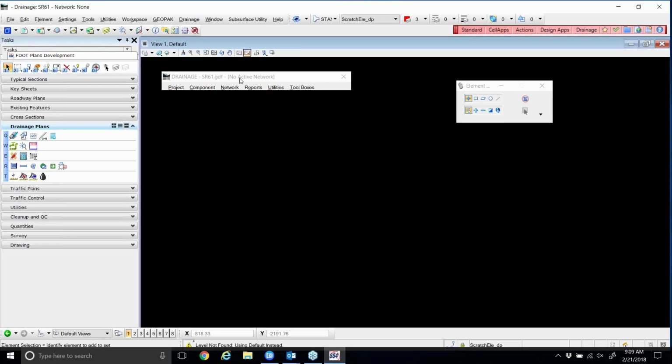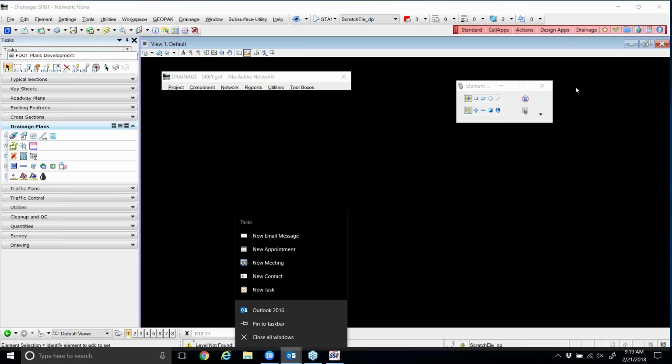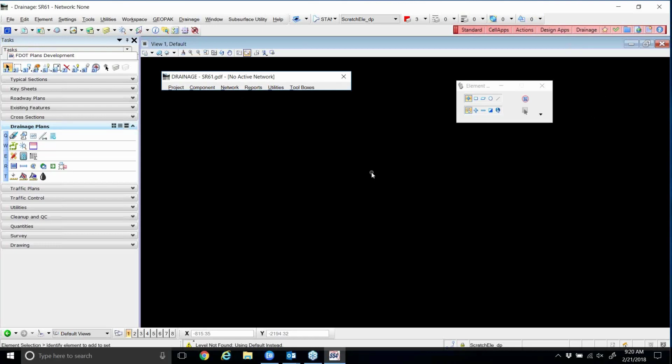So that finishes up chapter 1. We'll go ahead and get restarted here. Chapter 2 is going to be your drainage library. That's going to contain everything from these bullet points here, your rainfall data. We have land use runoff coefficients, where we can pick up that within our overall drainage area, we have a grass area, or we have an asphalt area, or we have some buildings. And as long as we use the correct symbology for those items, we'll be able to automatically delineate the runoff coefficient for those areas.